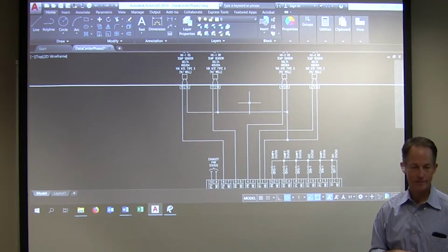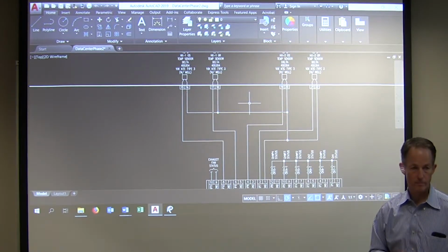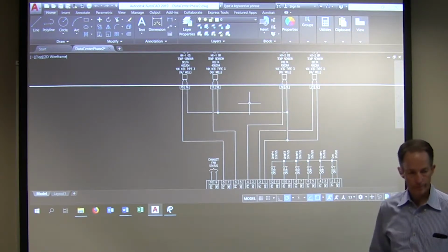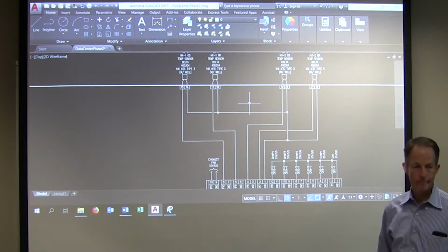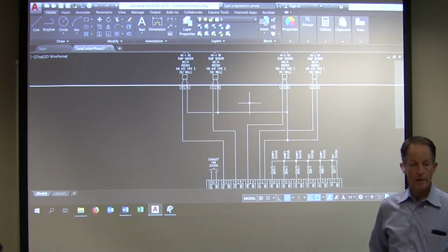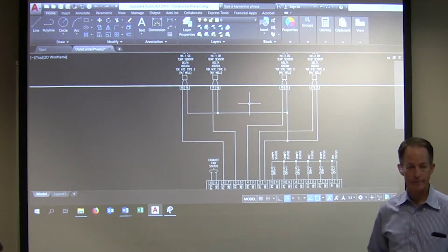Another thing to look at, like up at the Harmon building, they redid the controls on the air handlers, but from design, the drawings, things changed. So you look over them, they got some red lines, a few inputs and outputs have changed, and get that back to Atkinson or whoever's doing the controls, let them know we need to update these drawings to match what actually happened out in the field. It's really important.